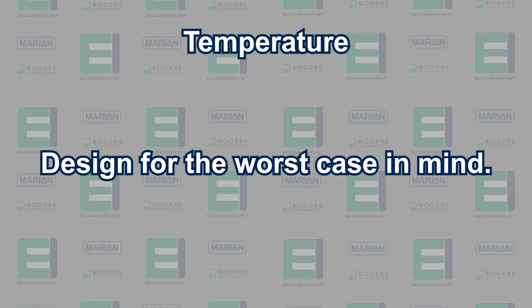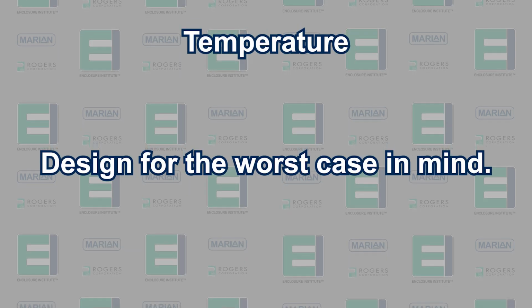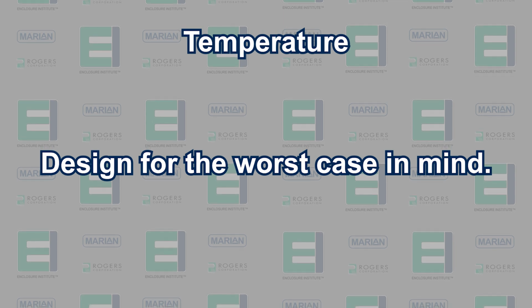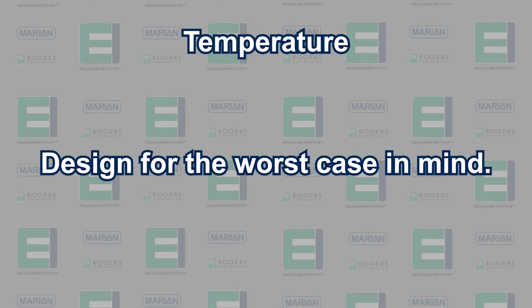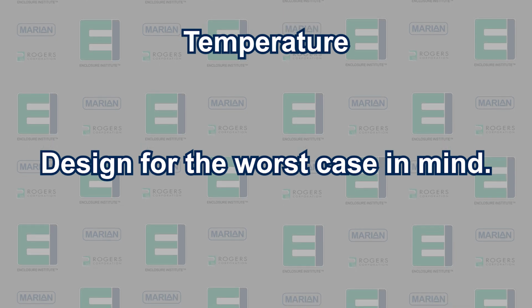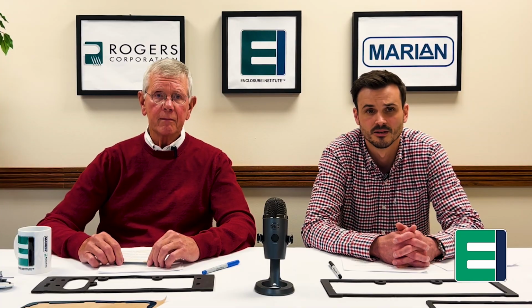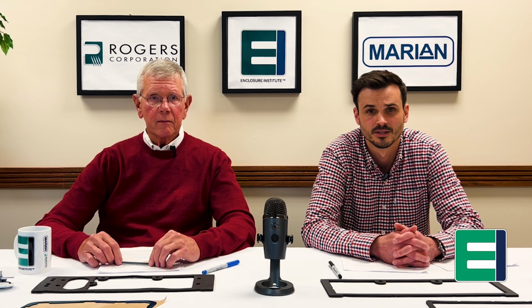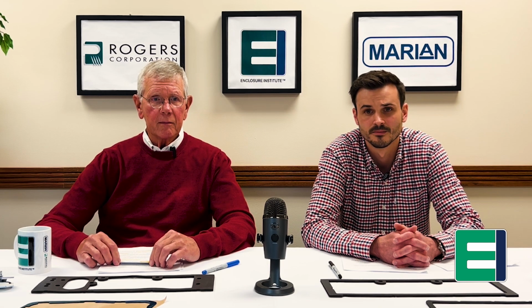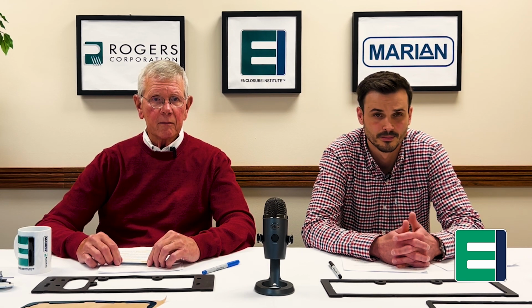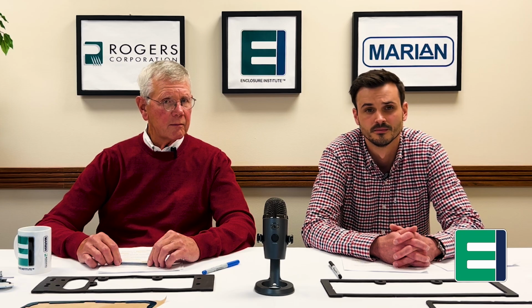To avoid this problem, you should design with the worst case in mind. Although your device might be used in ambient conditions most of the time, if it will be subject to higher temperature in some cases, then you should design for those times. Material manufacturers should be able to supply upper temperature limits for both constant temperatures and intermittent spikes. As we've noted before, silicones like Rogers BISCO materials offer the highest heat resistance at 200 degrees Celsius, while neoprene sponge by comparison tops out at 121 degrees C.